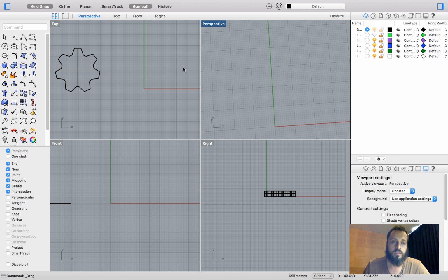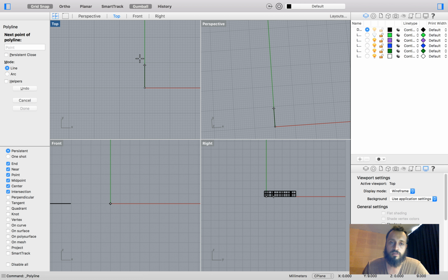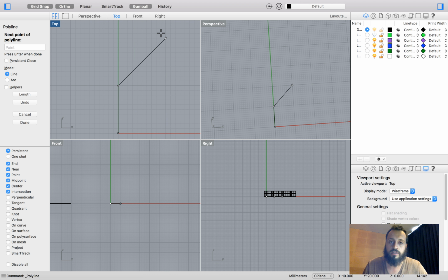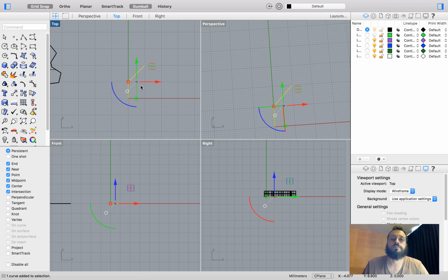For example, I'm gonna make many polylines. They're gonna be copies of each other. So I'm gonna make a polyline with a 10 millimeter length, the first segment. So you will see that it is restricted to that length. I'll press shift for orthogonal. I'm gonna draw another line over here, just by hand. So I have this segment, and I can move it around.